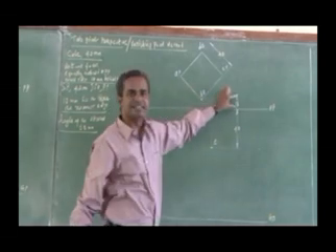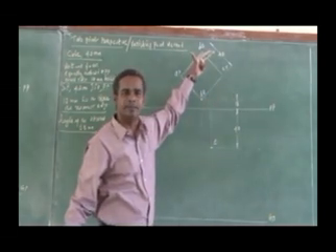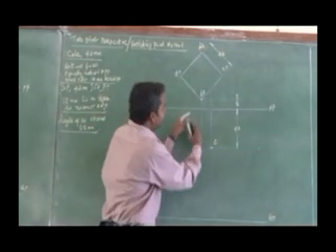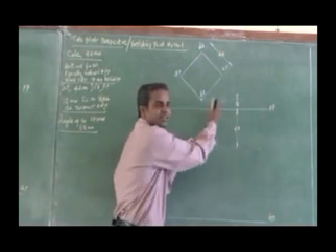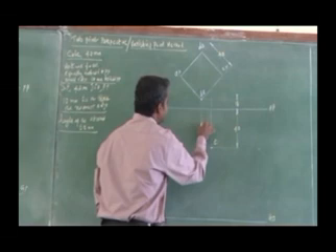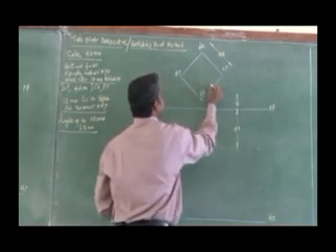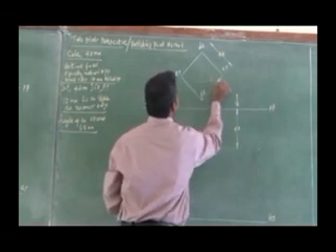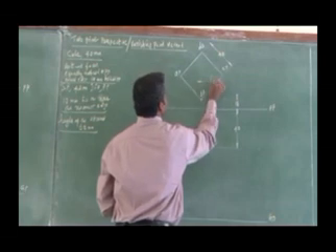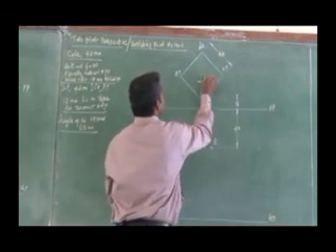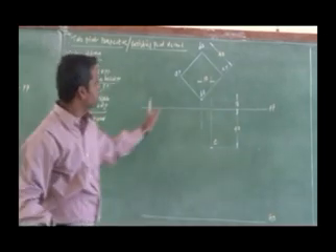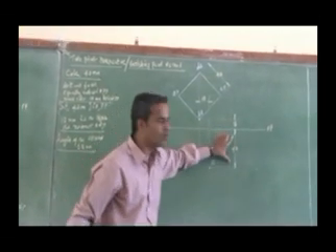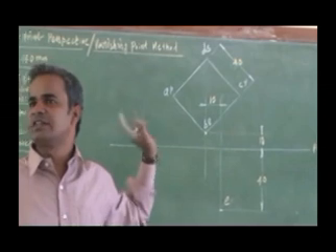That BQ nearest vertical edge is 10 mm behind the picture plane. Right. And the station point is given. It is 10 mm to the right of the nearest vertical edge. So this distance is given. It is 10 mm to the right of the nearest vertical edge, the station point. And the same station point E is 40 mm in front of the picture plane, that is given.